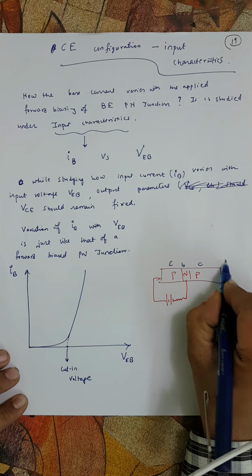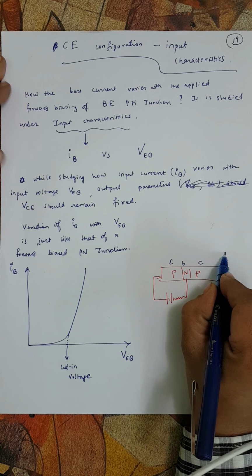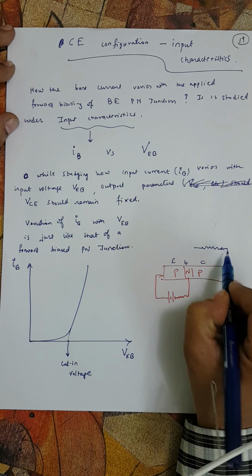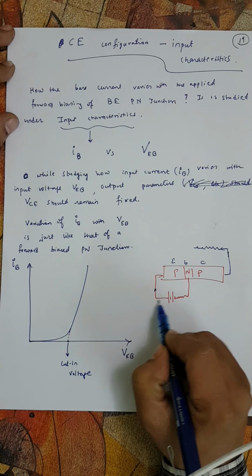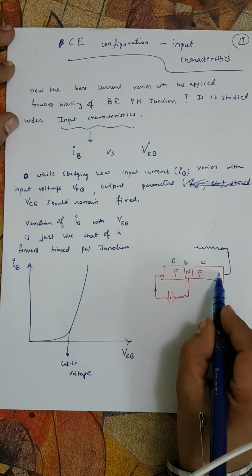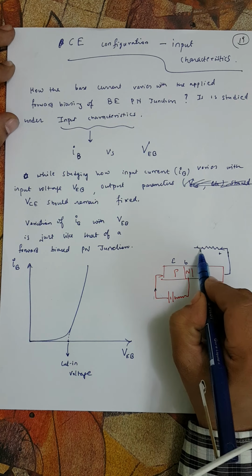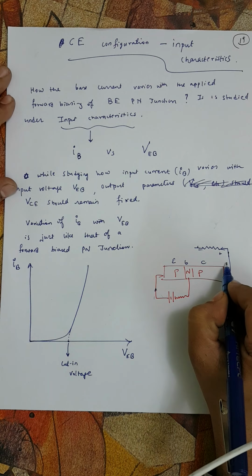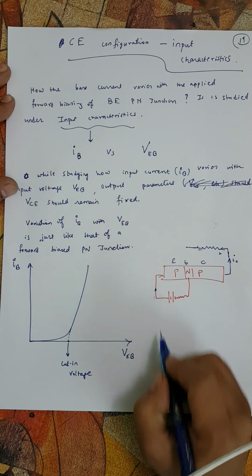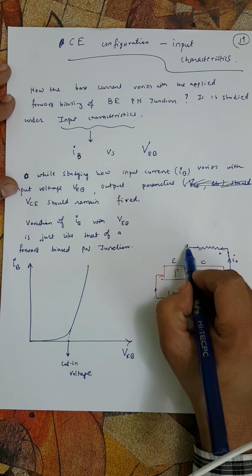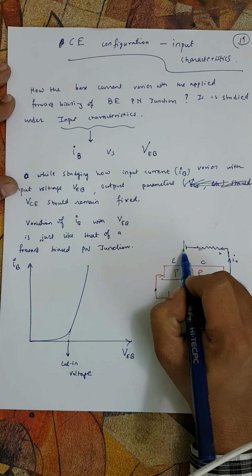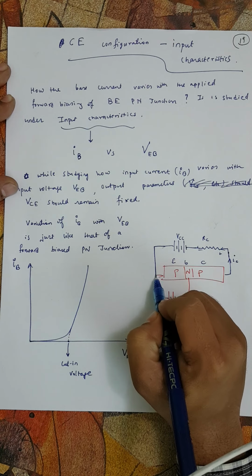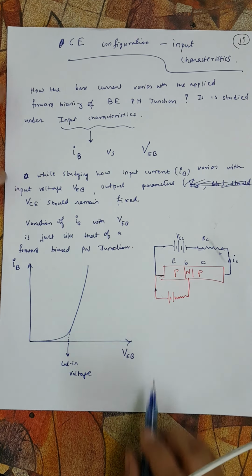This part of the circuit is called the output circuit, in which we have a battery and a resistor. Now obviously, as the current will flow here, because of the forward biasing, holes will be diffused here and these holes will come here, so plus minus. As we go from here to here, potential tends to decrease. So what we need is an increase in voltage, so that the collector base junction is properly reverse biased. So we require some battery, and we call this battery VCC. This is RC, and this is connected here again, and then this is the circuit. So this is called the output circuit.